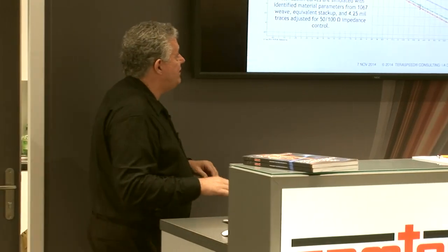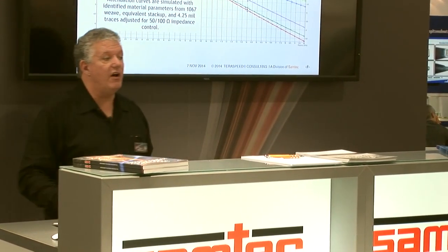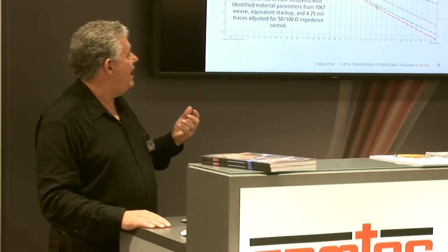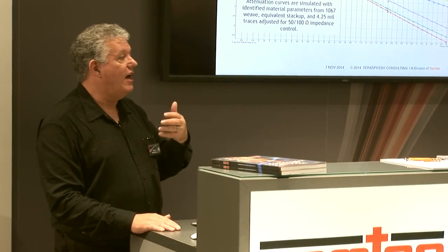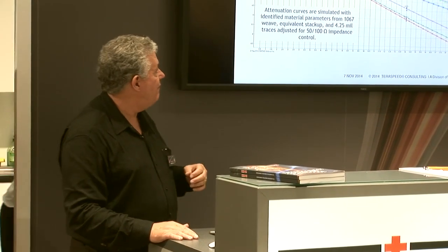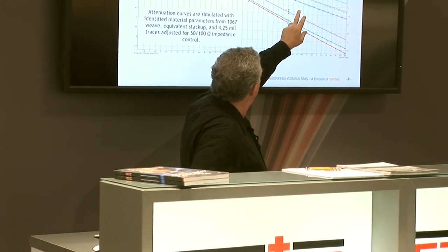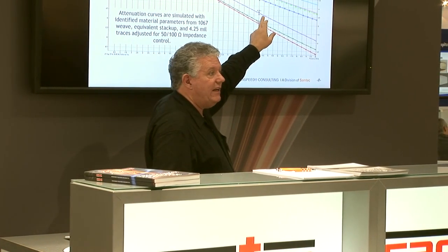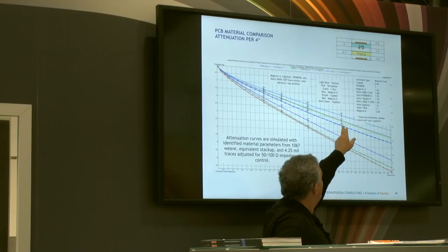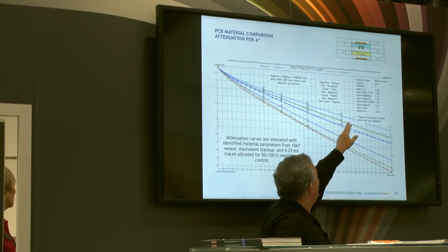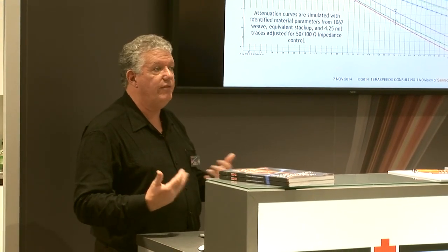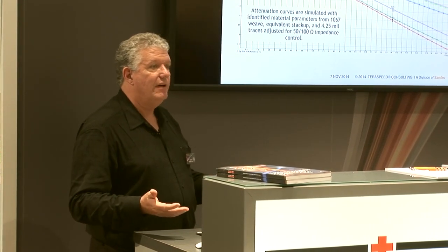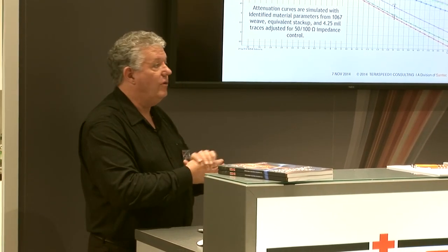Now, it's a fairly high loss material. It's about the same as Megtron 4. It has a dielectric loss tangent of about 0.01, and it's good, but it's not a high performance, low loss material. There are a number of other materials, such as this is Isola iSpeed. It's a bit better. It's a new class of materials. This is Megtron 6. This is Isola iTerra and Isola TerraGreen. TerraGreen is a high temperature reflow material designed for the most extreme European and US compliances.